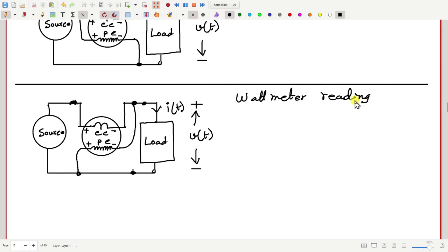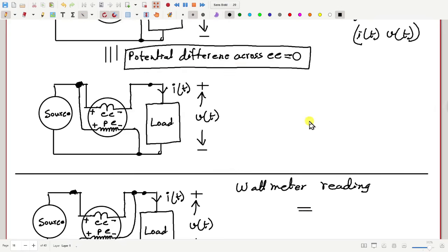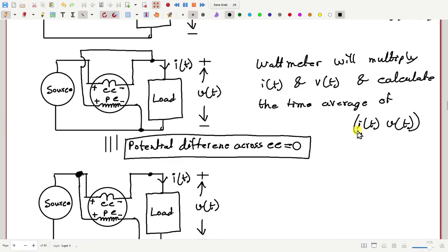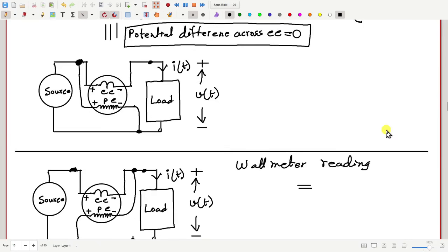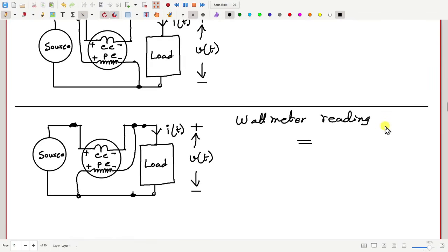Why same? Since it takes average, that's why. Yes, some of you said negative. Actually, it will become negative. Why negative? Because the product of voltage and current is negative for all time, right? Therefore, if you take the average, all quantities are negated, so the average will also get negated. So it will become negative even if you take the average.